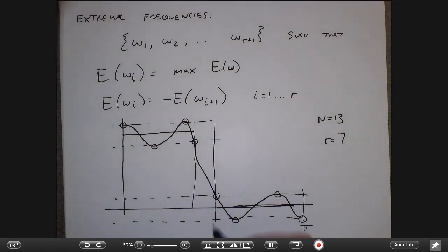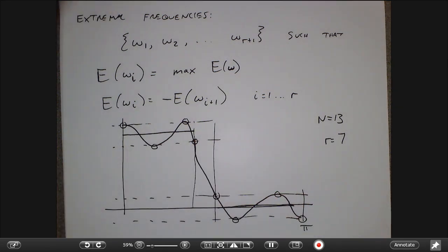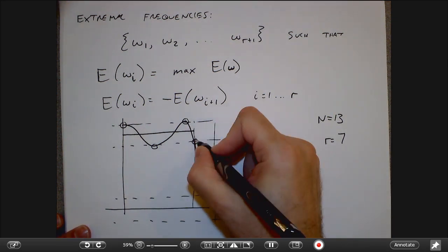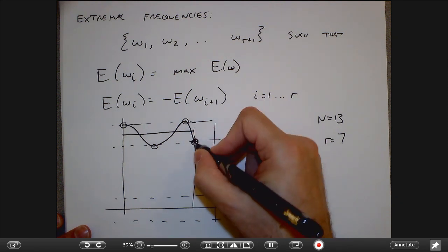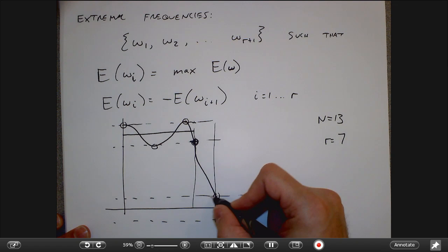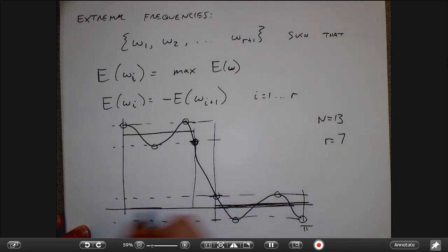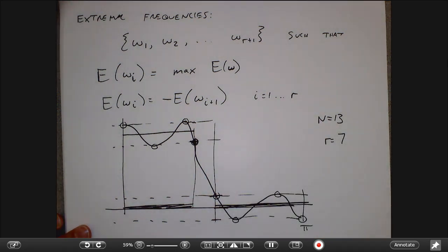And one thing to remember is that most of these places are actually local maxima or minima of the curve, but there are a couple places here, like when I'm going from the pass band to the stop band, where my error is exactly on the dotted lines, but then I kind of keep on going. But the thing to remember is that I'm only looking at the maximum error in the bands that I specify, right? So here I basically get the biggest errors at the end of this band, and then again at the beginning of that band.